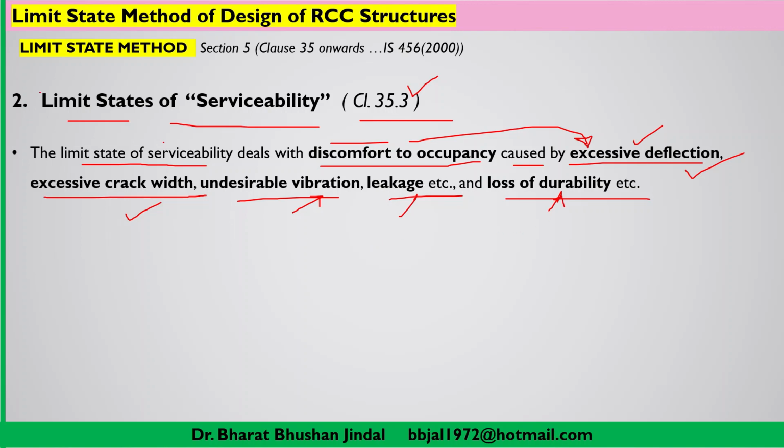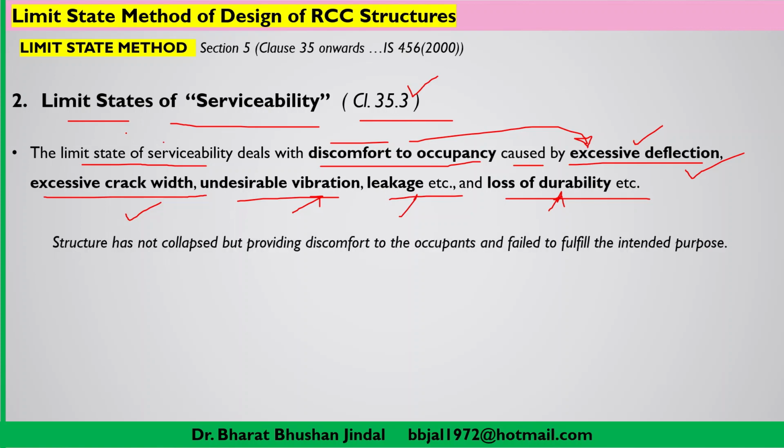All these parameters were not addressed in the working stress method. So that's why it is the limit state of serviceability. Now we can understand that the structure has not collapsed, but it provides discomfort to the occupants and fails to fulfill the intended purpose for which it is made.